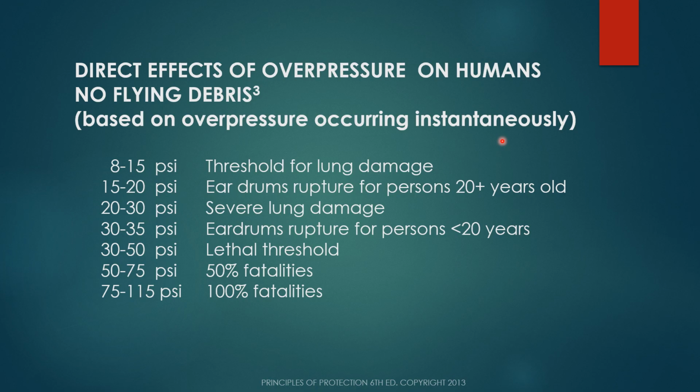If he goes 20 feet deep, he's going to experience 8.8 psi on his lungs and his eardrums, instantaneously. So just to give you a reference point, those kind of pressures we do deal with normally. But again, 10 psi is about the limit, because what happens inside a shelter is not instantaneous. It's over a couple seconds.